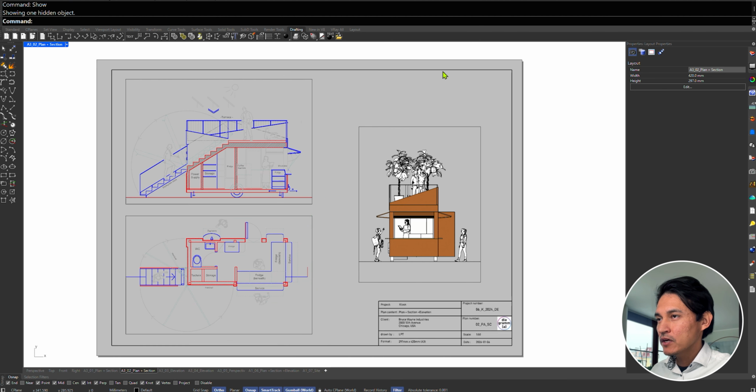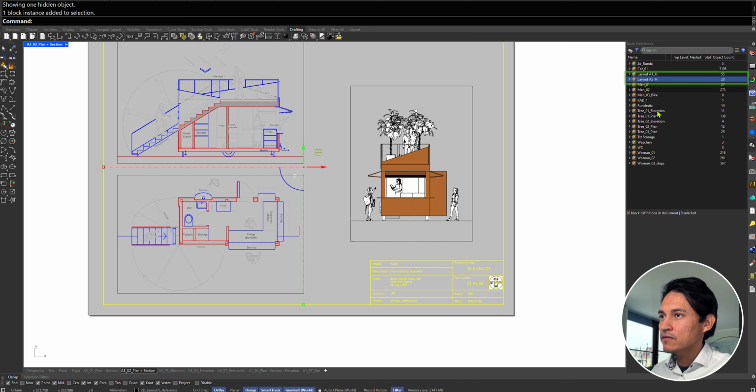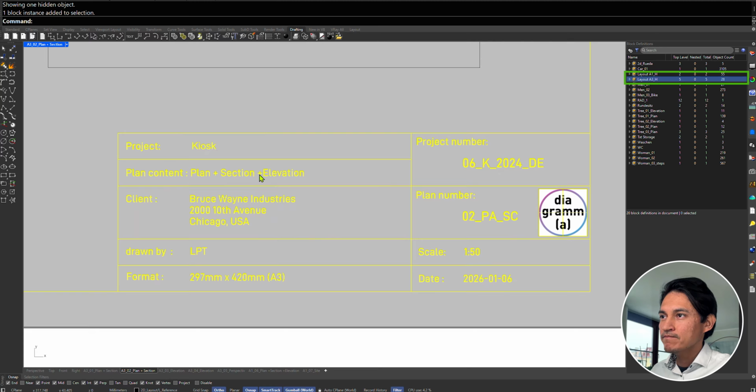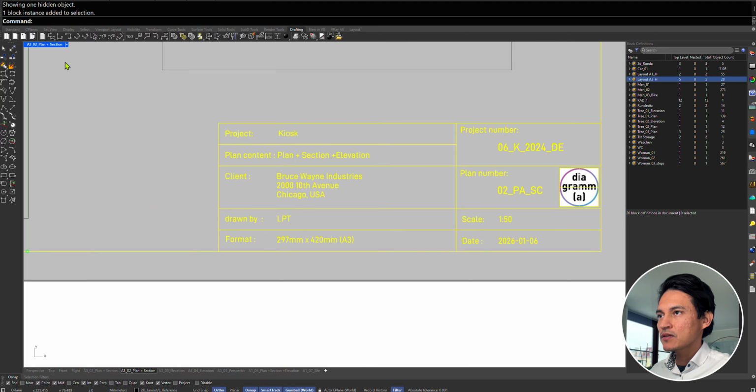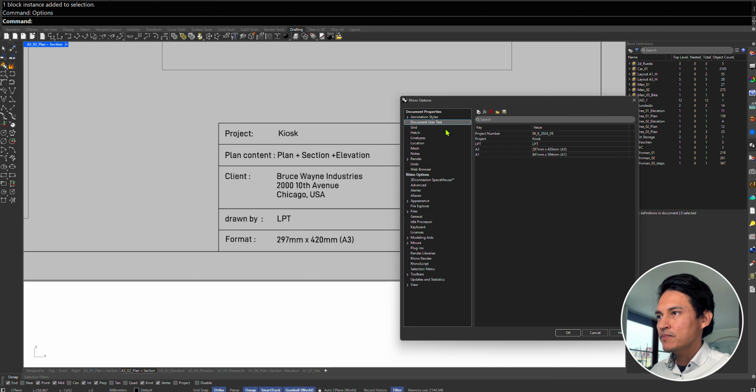If you have lots of layouts, it is advisable to work with title blocks as 2D blocks for the different formats you may have. Then you can copy them everywhere you need them. From the document user text, which you find in options, it is possible to link text information, like the project number or the project name, in the title block by using text fields.